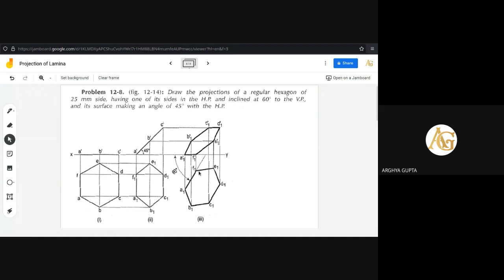Okay, so once they are found, now draw horizontal lines from these 3 points, and vertical lines from these 6 points. Okay, so all the points will meet. So A1, A, so it will be on the horizontal line. F will be on the horizontal line, so AF is found.